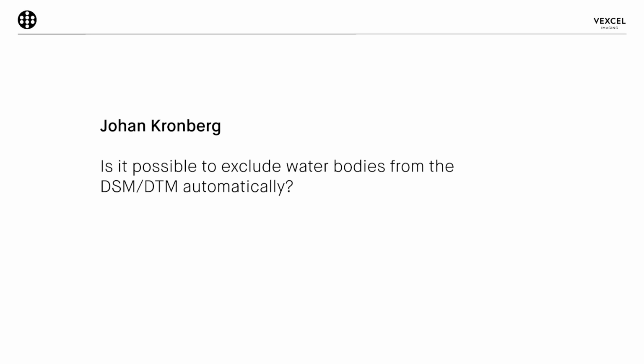So with the new approach with image segmentation, we now have a new detection of the water bodies in the workflow. Right now, the processing step which takes most benefit of that is the color balancing. When you compare a color balancing mask from V5 to the color balancing mask of earlier UltraMap versions, you will see a great difference. And now the color balancing mask is a very, very detailed representation of the water body.